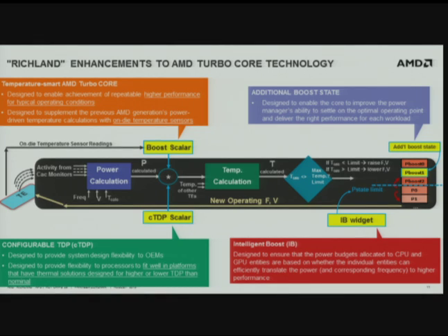In the previous generation product, each of these control loops, operating independently, would run towards using up all the thermal headroom, meaning they can raise their frequencies and whatnot. But it's quite possible that the raised frequency is not really resulting in performance. So you can detect those cases, and if you throttle those entities, you can give that thermal and power headroom to some other entity. That's the concept there.